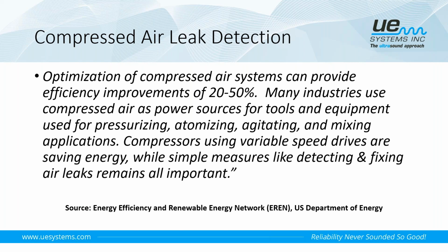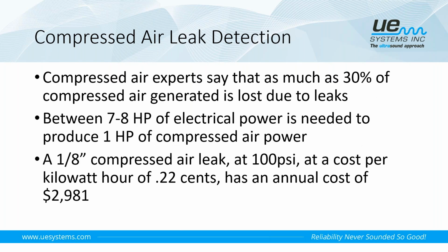But I tell you, a great place to start is simply going out and locating and then repairing compressed air leaks. The Department of Energy says that optimization of compressed air systems can provide efficiency improvements of 20 to 50%. And again, one easy way to do that is through going out and not only finding, but also repairing compressed air leaks. You've got to repair the leaks in order to realize these savings.